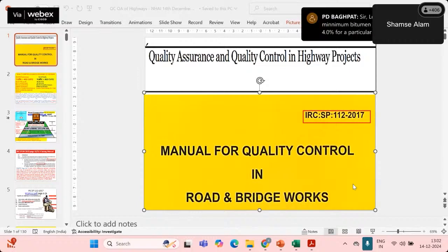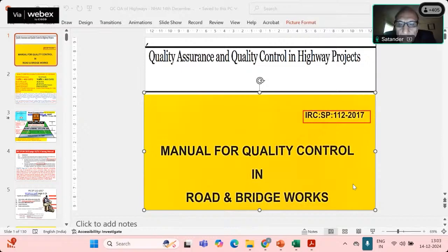Sir, in PQC road, if the main criterion for acceptance of the test is the flexural test, then why are we casting the cubes? Very good question. See, why we have given cube also, this we discussed in our meeting also. The reason is, when you are casting a beam, there are chances of not getting accurate results because its weight is very heavy.